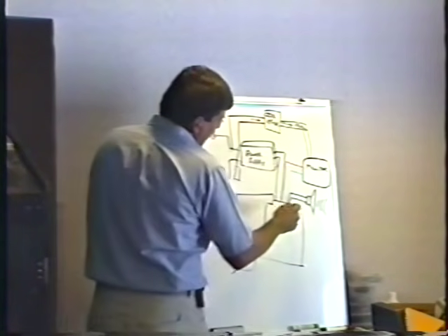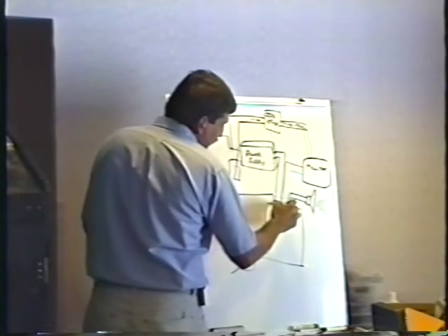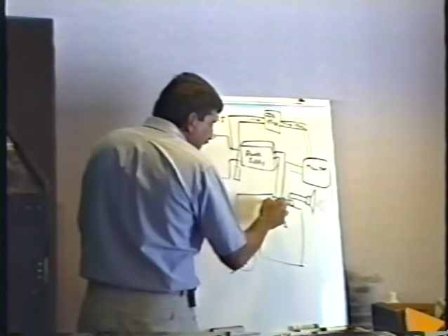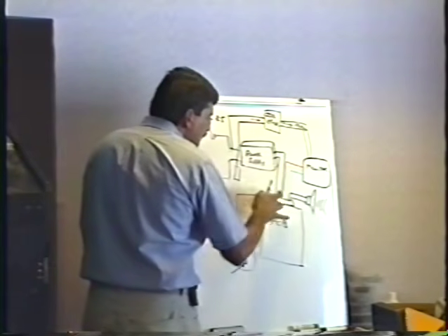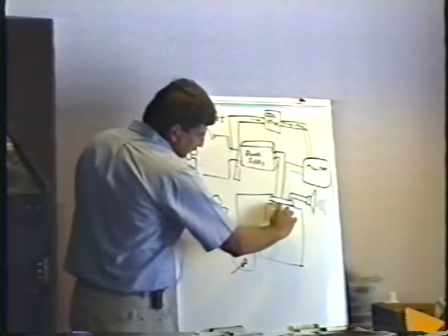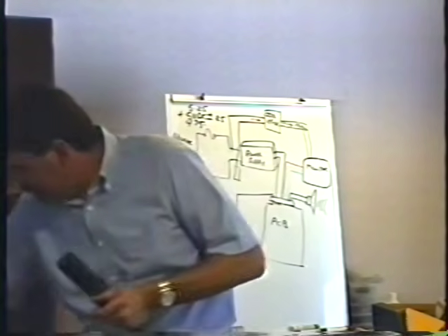So where I check the voltage is here at the connector, on the JAMMA harness. When the connector that's on the wires is connected to the card edge, there's a little bit of the little plated finger sticking out from behind it.